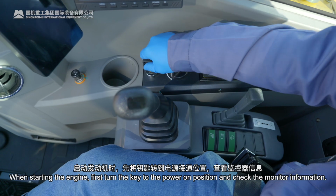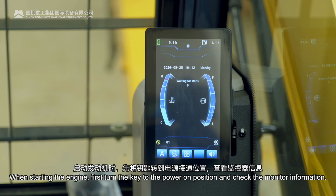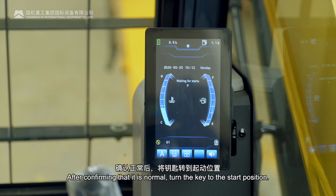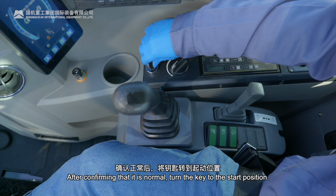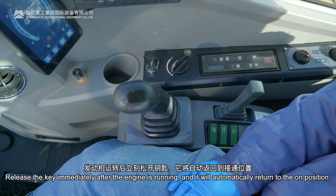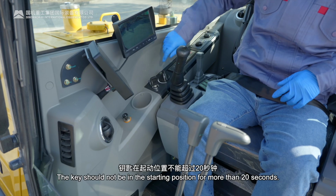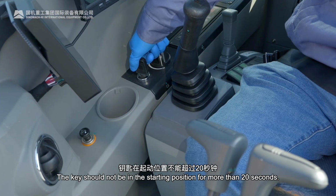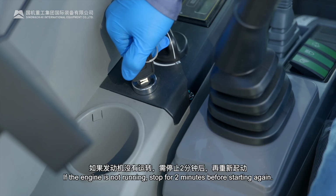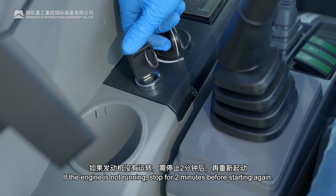When starting the engine, first turn the key to the power on position and check the monitor information. After confirming that it is normal, turn the key to the start position. Release the key immediately after the engine is running, and it will automatically return to the on position. The key should not be in the starting position for more than 20 seconds. If the engine is not running, stop for 2 minutes before starting again.